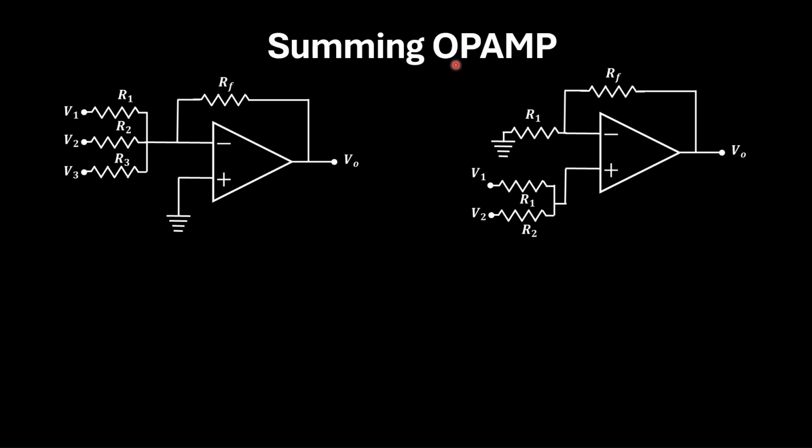Now we will discuss summing op-amp. In summing op-amp, multiple inputs through resistors will be applied to the inverting terminal, or multiple inputs through resistors will be applied to the non-inverting terminal. Now let us try to learn how to find the output of such type of circuit. Now here the voltage is 0 volt, so similarly here also it will be 0 volt, and whatever the current flowing here, the same current will be flowing through RF.